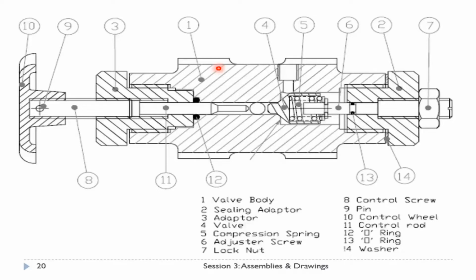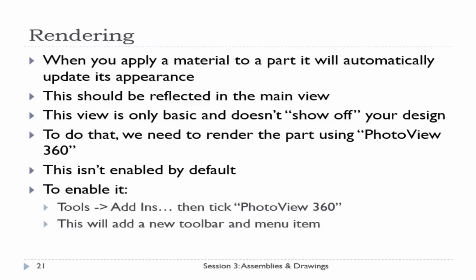So insert the valve body and resolve the fixed state, just make sure it's fully defined, and then bring the other subassemblies and the other components. So the only component that you wouldn't be able to find in the toolbox is item 5. There is no compression spring under the toolbox standard folders. So you can either leave that blank, or using the spring modeling method we discussed in the second session, you can create a spring model fitting inside the valve.